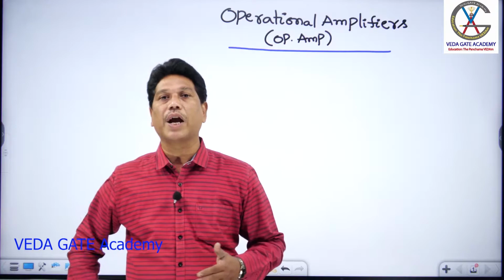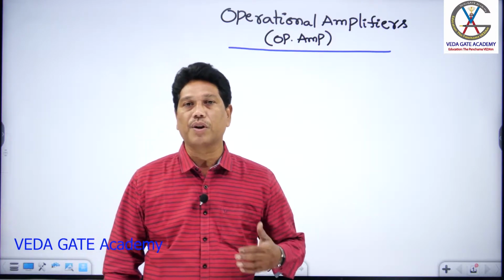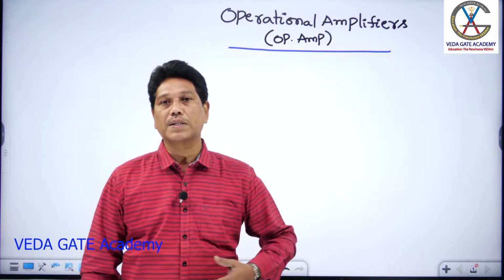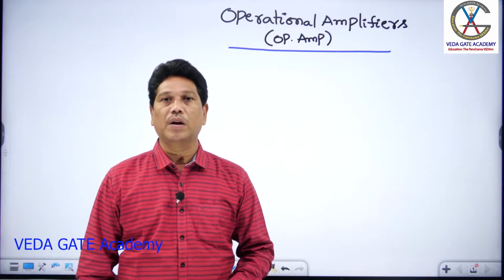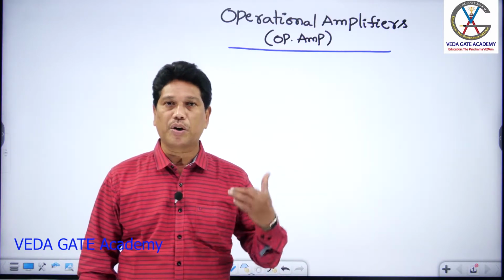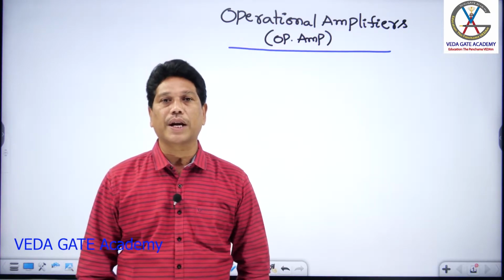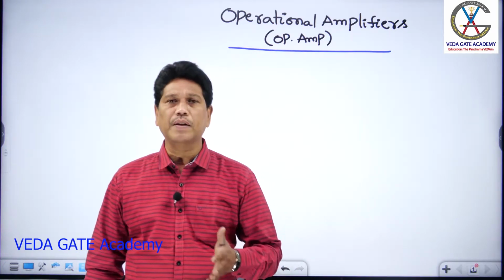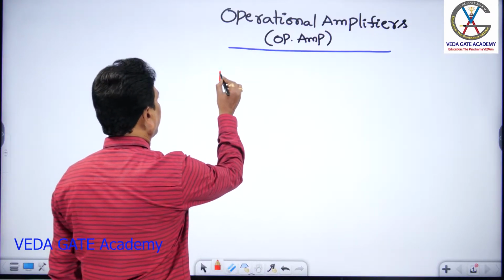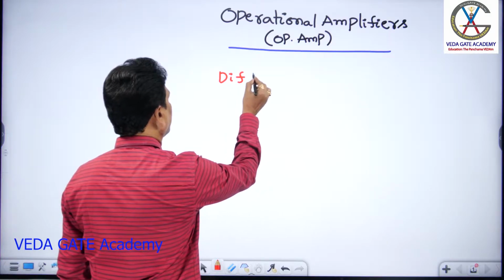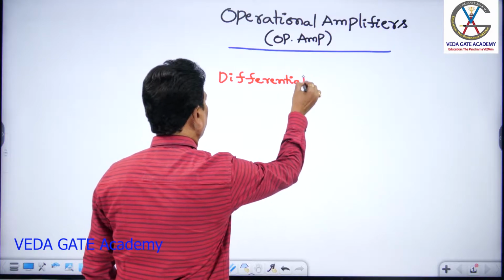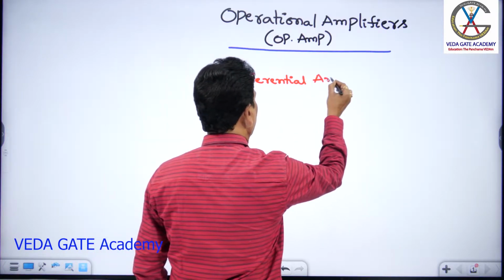It has a very high gain, and it is a direct coupled circuit. Small signal amplifiers use capacitive coupling, large signal amplifiers use transformer coupling, and this integrated chip body of operational amplifier uses direct coupling. The mainstay in the case of operational amplifier is a differential amplifier.